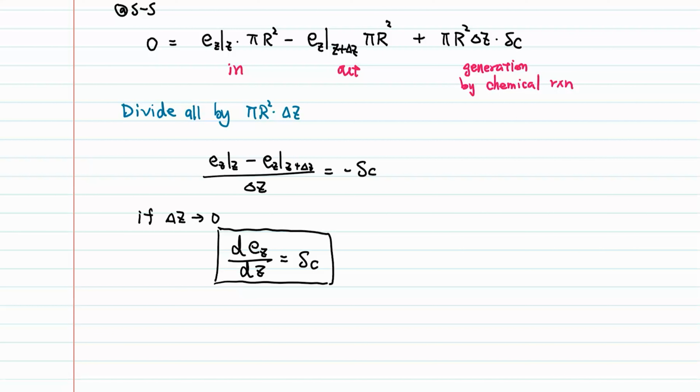Okay, so again, if we revisit the combined energy flux vector, we have the convective energy transport term plus delta H times Vz, convective, and we have heat, and we have work by shear stress, right? And again, let's analyze this one by one.